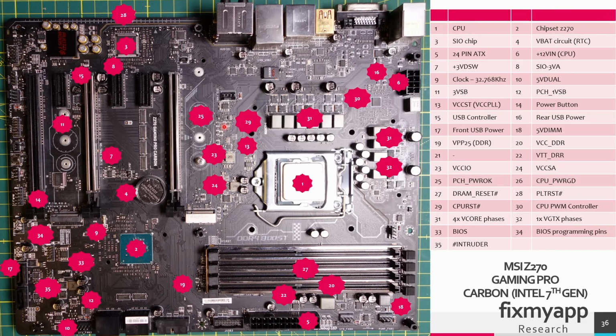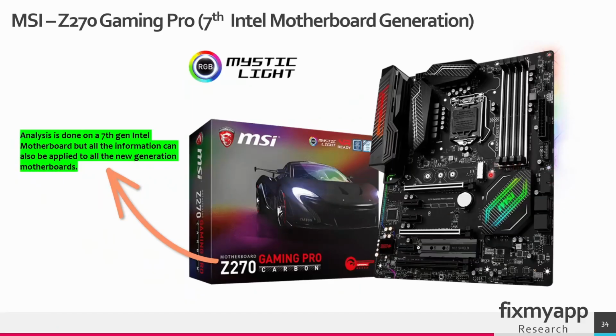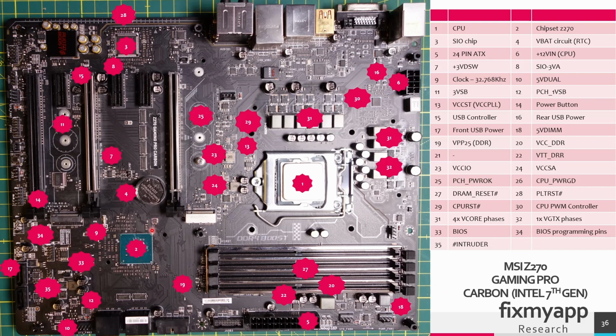Let's identify the most important components on this Z270 mainboard. This is the CPU and this chip here is the chipset Z270. I have removed the rectangular heatsink that is above this chipset. So normally it looks like this. On the other side, this is the Super I/O chip. This chip is responsible for managing legacy and low-speed input-output functions that are not handled by the CPU or the chipset itself.